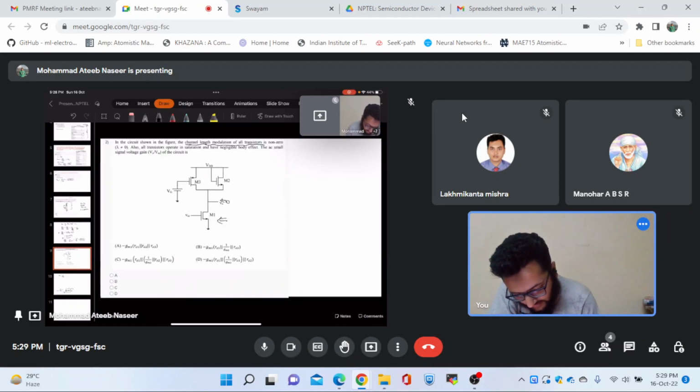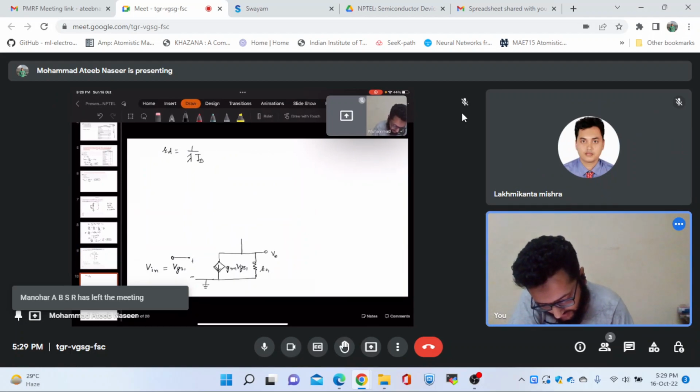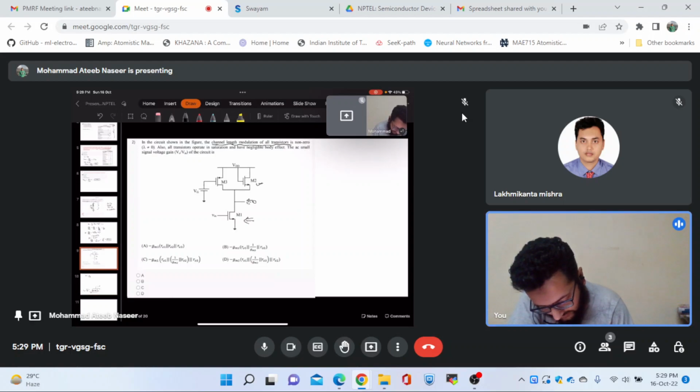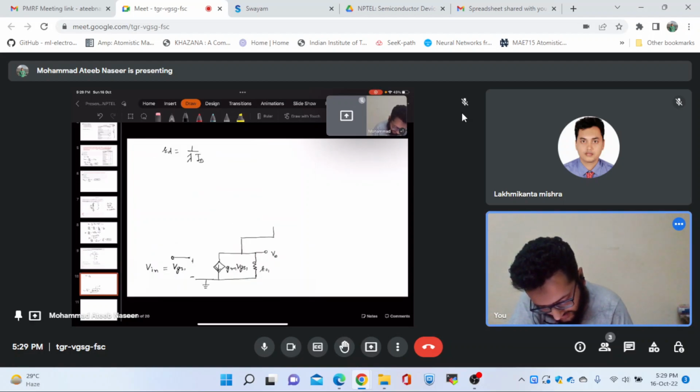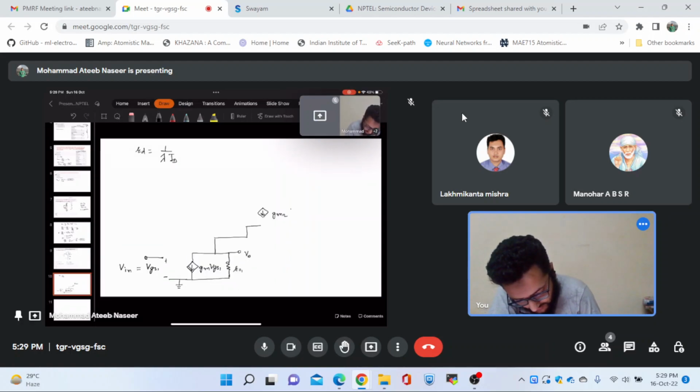Let us see the another transistor. Let me draw M2 or M3 first. Let us draw this M2. This is its source. Okay, their source is connected to this, and this is gm2 vgs2, I think its name is 2. Yes, gm2 vgs2, and we will be having its r0 2.